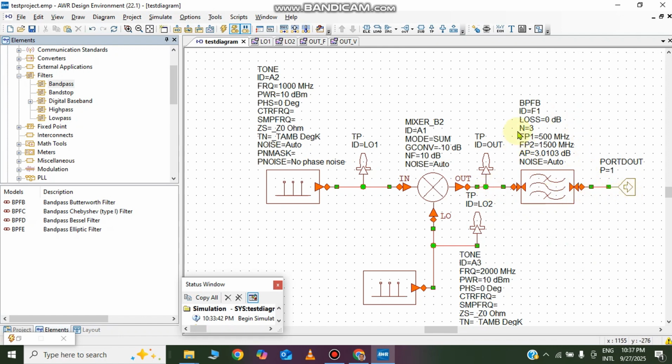In here in the settings, I need to specify the FP1, which is the minimum lower level of the frequency range, and the FP2, which is the upper level of the frequency range. Because we need to have 3000 megahertz, I will specify 2900 megahertz. Press OK, enter, and then 3100 megahertz. Press enter. Okay, and I will add another test point in here.